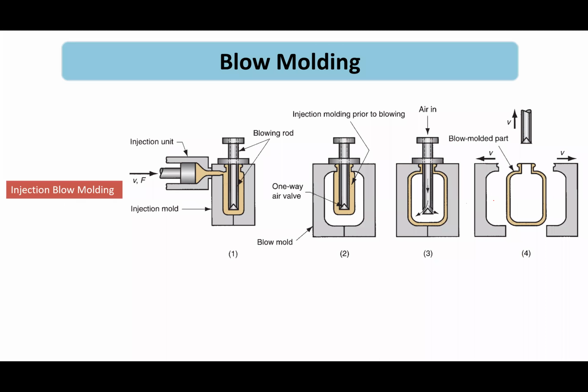All right. Then this is another type of blow molding, injection blow molding. It actually uses the benefit of injection. At the same time, the process is very fast compared to the previous one we have studied. In this case, the molten material is injected using a plunger in here, into the cavity of a parison. The parison is made in here. This one is called parison.